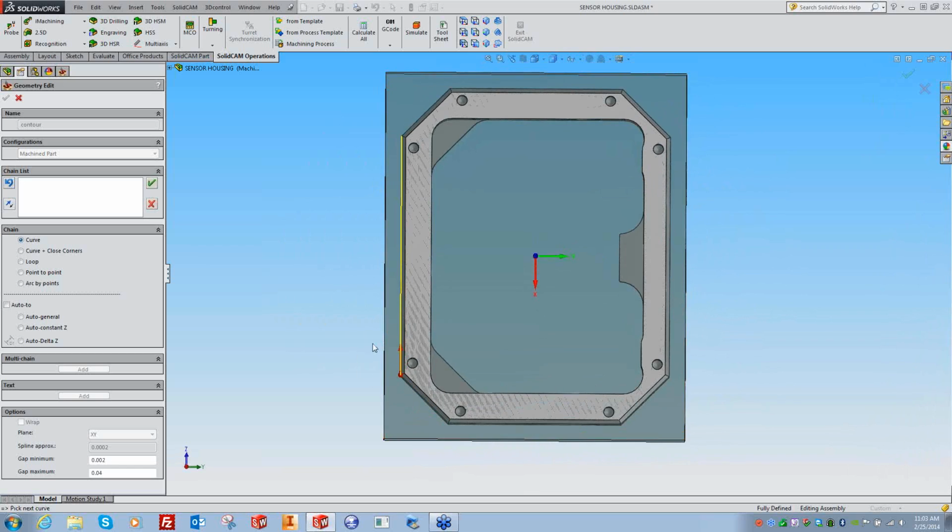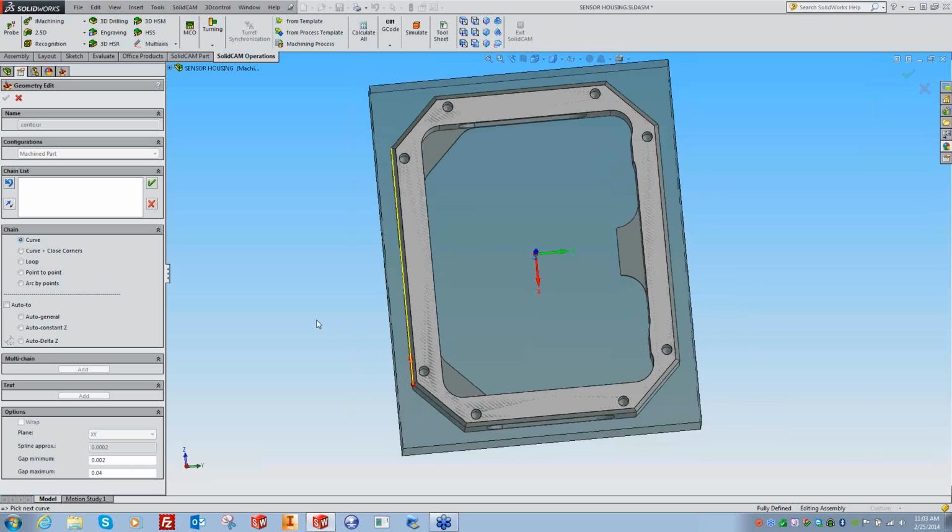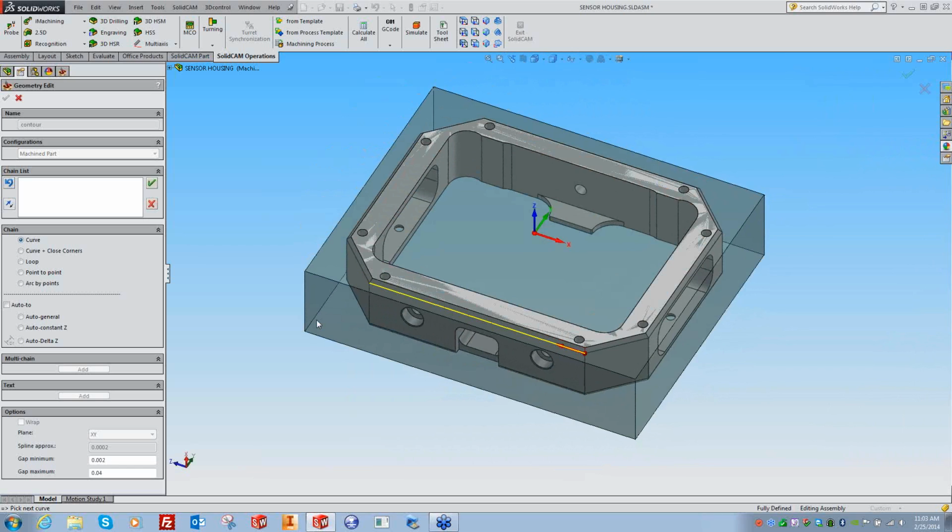This is the direction the tool is going to go, and in profile mode the tool always defaults to the left side of the line, so you're doing a climb cut. Now you can switch it to the right side, but then you'd be doing a conventional cut and you'd be on the inside, or you can put it to where you're cutting dead center if you'd like, and we'll get into that. So it's important to note where your start point is.